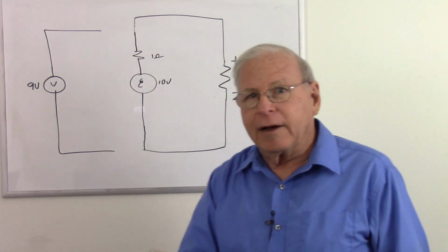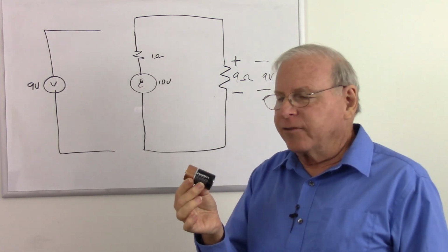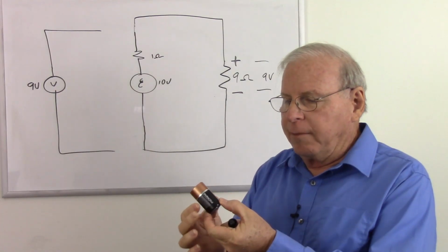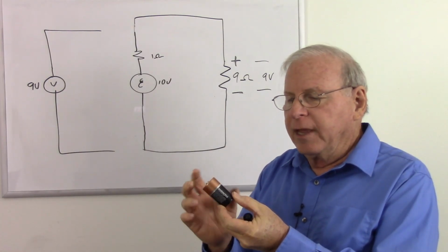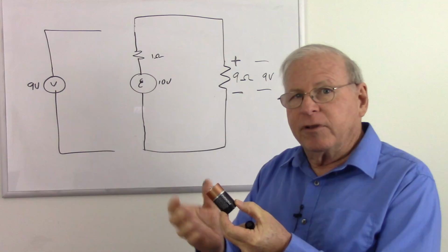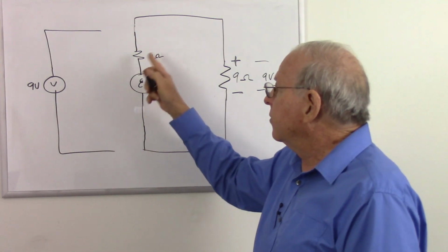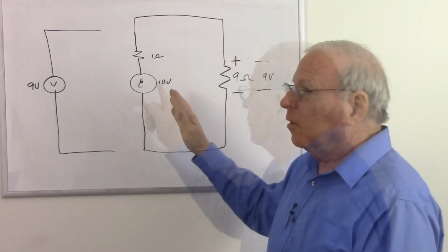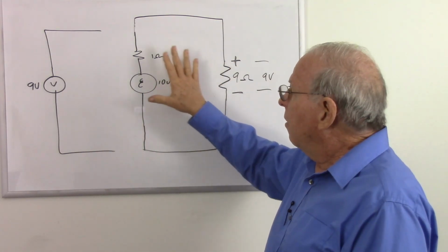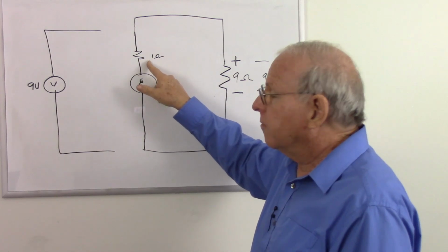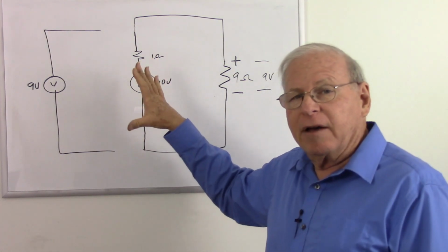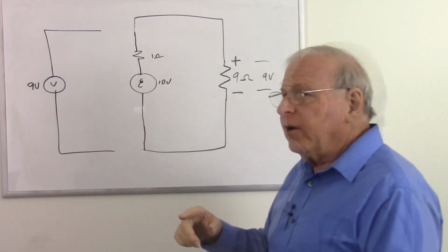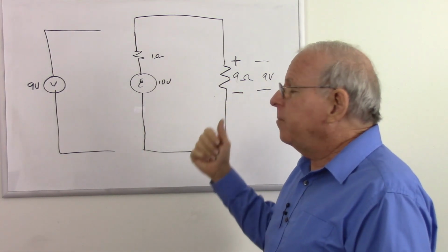And also, I pointed out that a battery also has electromotive force in it. It's chemical instead of electromagnetic, but it's the same thing. We have an electromotive force in here that is pushing current, and we have a resistance in here, and it works out the same way. This could be a battery, or the secondary of a transformer, or the winding of a generator. All of them work the same way, and we find that our resistance goes in series. And when we have AC circuits, the impedance would go in series also. So there is why the resistance appears in series.